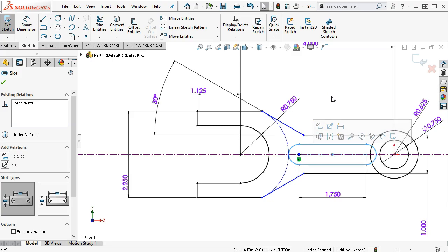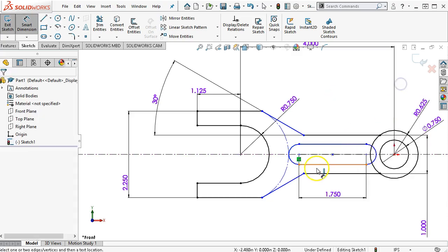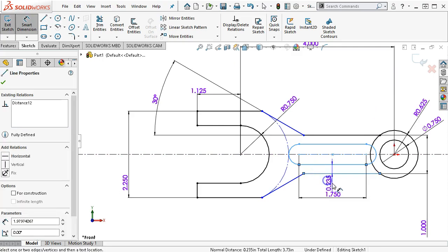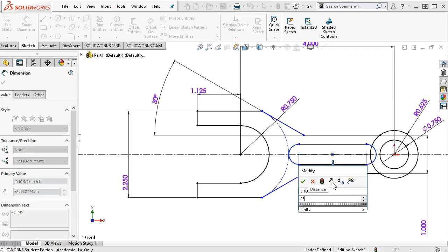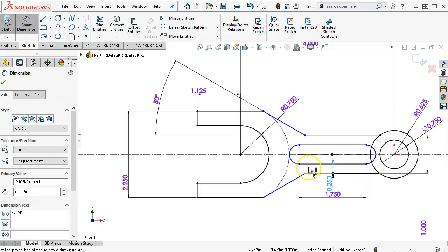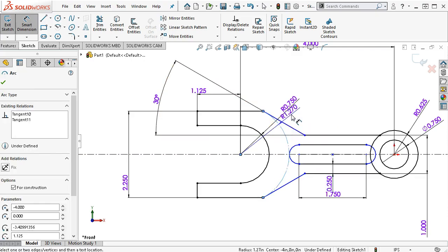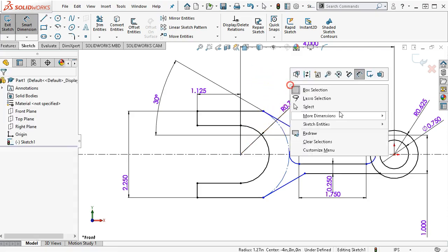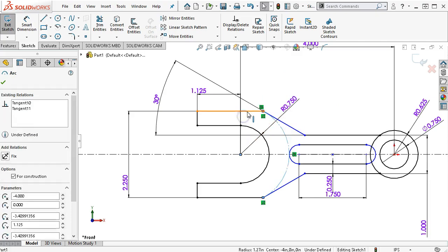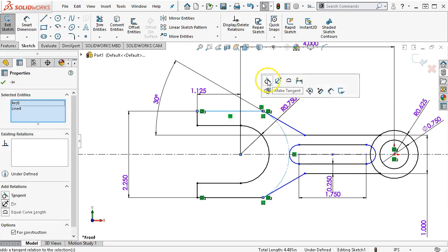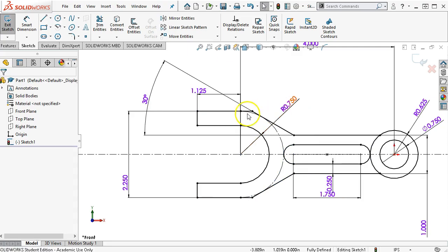Let's see, what do we have? Radius, or 0.250 typical off of the side wall. Okay, so I would put it at a half inch. And if they're going to do that as a radius of 0.125, well, that would just make that tangent. So in that case, let's see what that looks like. We'll go ahead and Control-select, pick up tangency. All right, so a little bit of a gap. That brings it up to the radius. It also happens to look like it's touching at the end circle.